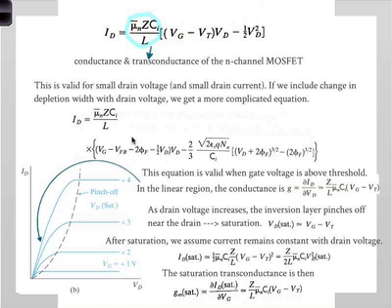That's when the depletion eats into the inversion layer. The inversion layer disappears at some point near the drain. So think about what you just said for a second. Now I have current saturation without pinch off. Right? Which means that almost all of today's transistors almost always operate under saturation. You don't need to have pinch off.